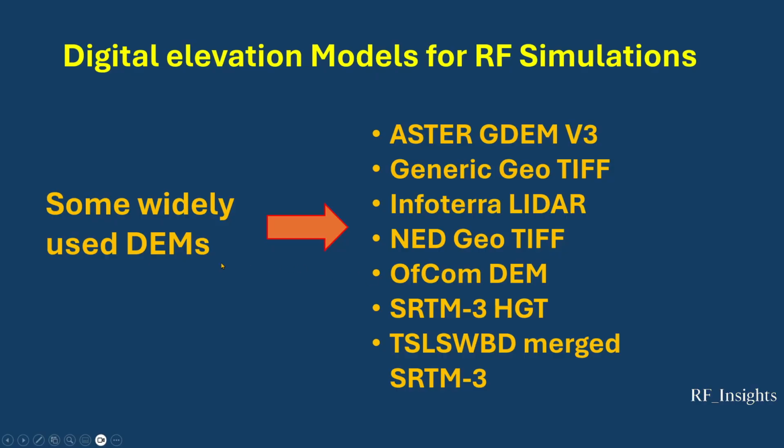So here you can see a list of commonly used digital elevation data that are used by common RF simulation tools. I personally use the first one, ASTER GDEM V3, for my simulations. This has 3 meter accuracy, which is sufficient for the purposes of my study.